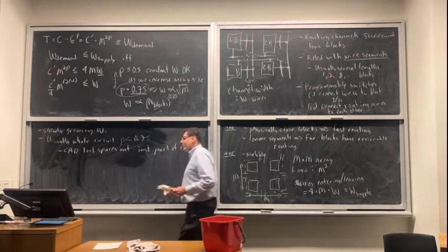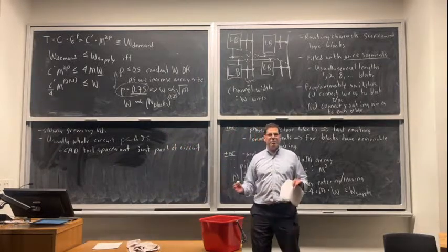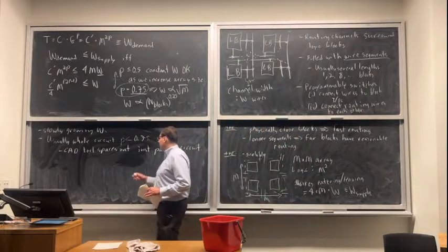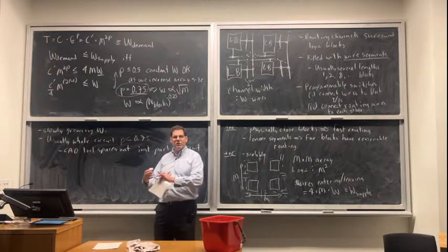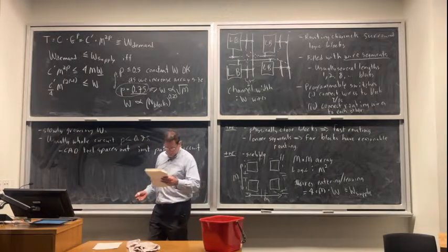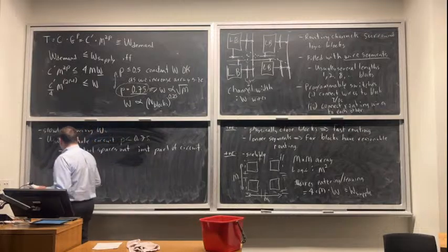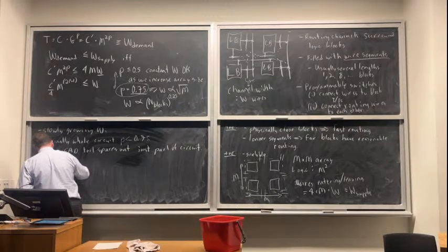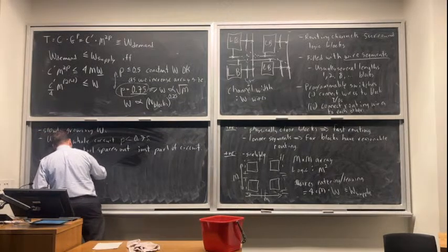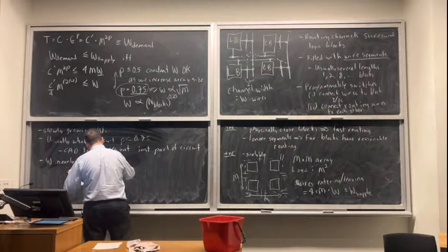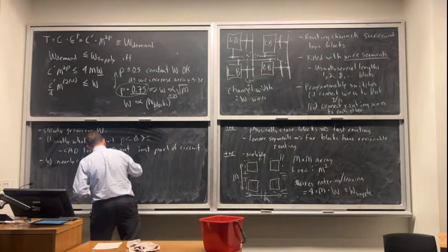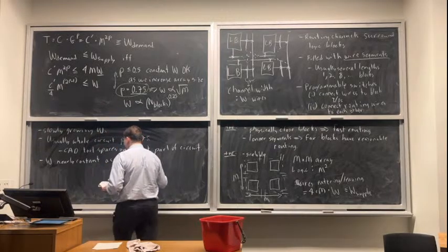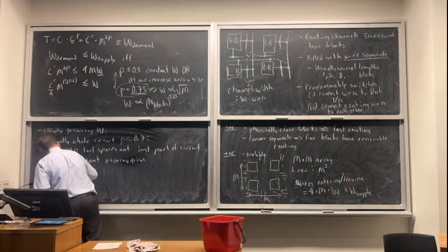Okay. So I've been talking about this like a whole circuit has one Rent exponent. You can have sub-pieces that behave somewhat differently. The control logic is usually worse locality, but again, the CAD tool can just find those pieces and space them out. You need a reasonably advanced CAD tool to do that though. Okay, so what this means is W nearly constant as your array grows, if you have good placement.